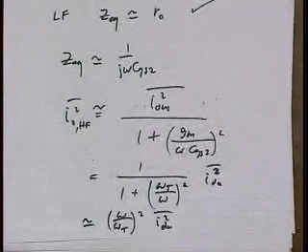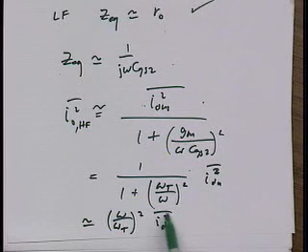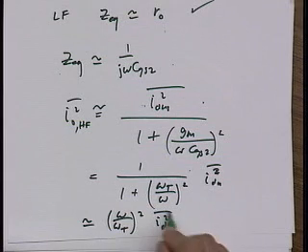This is the exact expression that we had in the slides, which told us that the drain noise at high frequencies starts to matter with a ratio omega over omega t. Or in reality, this is slightly lower than omega t. But the important point is that it's really at high frequencies that this noise starts to kick up. Okay? Questions?